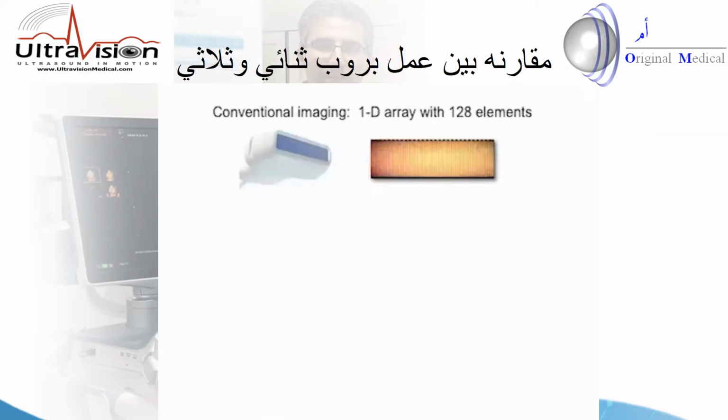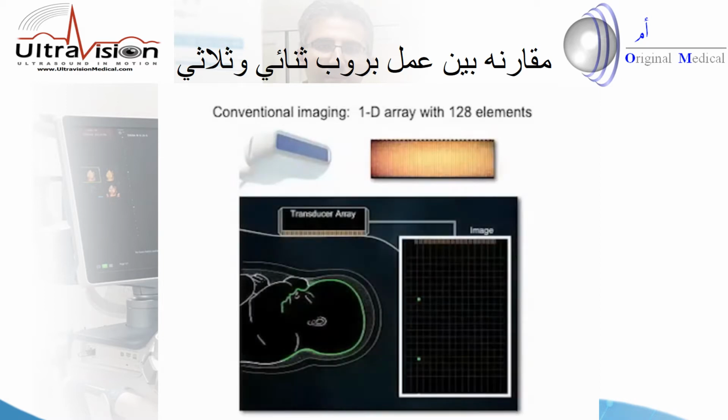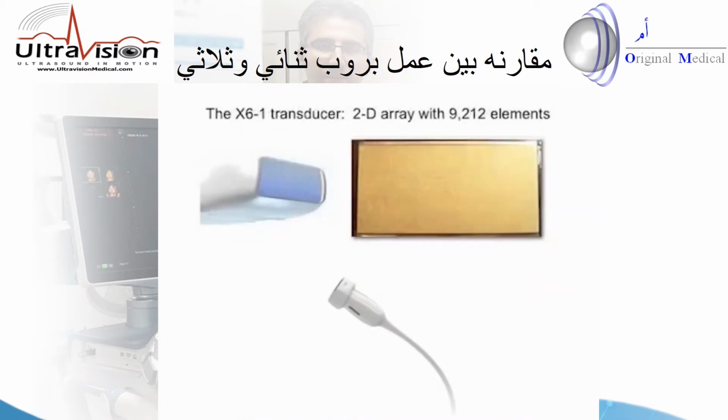has a number of elements aligned in a row, and these elements are excited in groups and echoes detected one at a time to form the lines of an image, perhaps 100 or 200 lines that make up a B-mode image. And the plane of this image is defined by the direction that the transducer is pointing in, and if we want to change that plane, we have to move the transducer either with our hand or with a motor in some transducer probes.